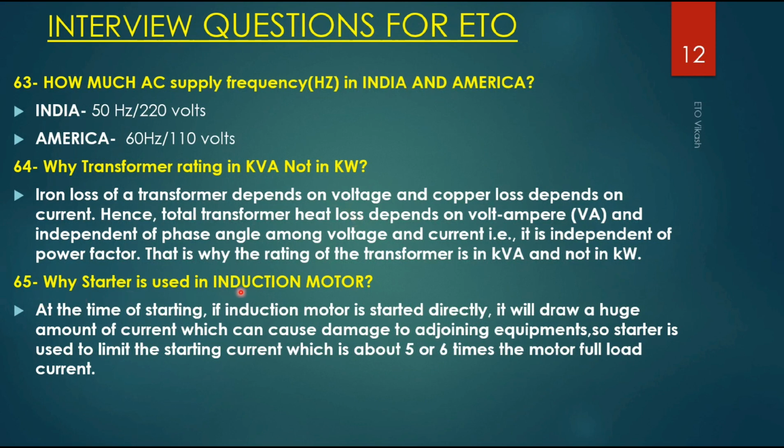Why is a starter used with the induction motor? At the time of starting, if the induction motor is started directly, it will draw a huge amount of current, which causes damage to adjoining equipment. So the starter is used to limit the starting current, which is about 5 to 6 times the rated current. It is also used for the safety of the cable and the safety of the motor.